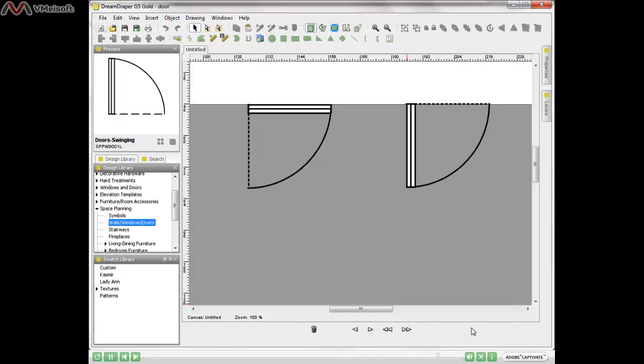Now just a little note about the placement of doors. Some designers will place the door in the closed position as seen on the left. Others place the door in the open position as shown on the right. And I've seen some designers position the door something like this. And you don't want to do that because then you're not going to have enough clearance along the bottom. If we measured our door at 32 inches, we've now moved that door outside of the perimeter, and so you won't have enough clearance for that door to swing.